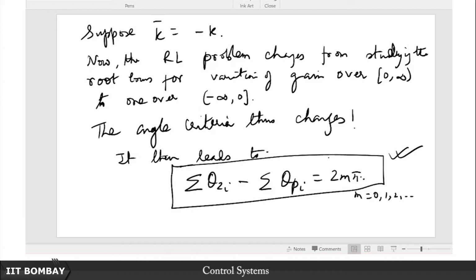So if for no value of negative k that Routh table first column turns out to have a sign swap, then there is going to be no migration of roots, okay. On the other hand, if there is a negative value of k at which one particular row becomes all zeros, then you will have some migration happening at that point,